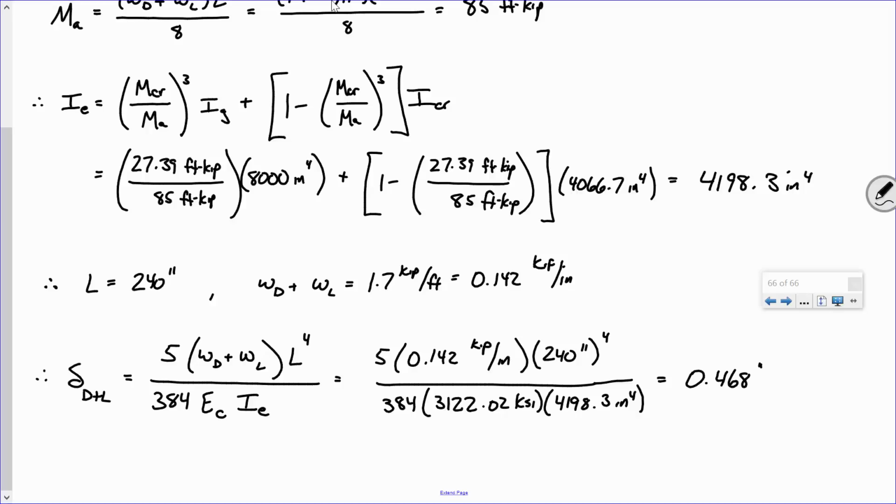All right, think about it like this. If you're correct that we can just remove that and use just the live load, then we should be able to remove this and just look at the dead load. So we can compute dead load deflection, right? But would you get the same answer here as you did before? Your I changes. You see what I mean? Really, the only way to do it is to compute the dead load deflection, compute the whole deflection, and take the difference. It sucks, I know. In steel, it's not that complicated. In steel, the material properties don't change, so you don't have to go through all of this. All right, has everybody got all this?